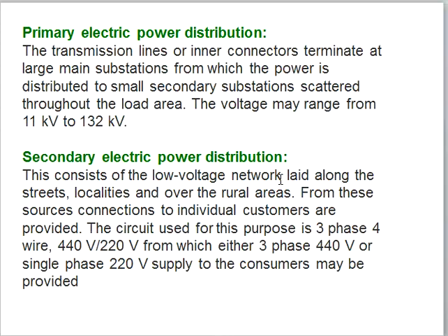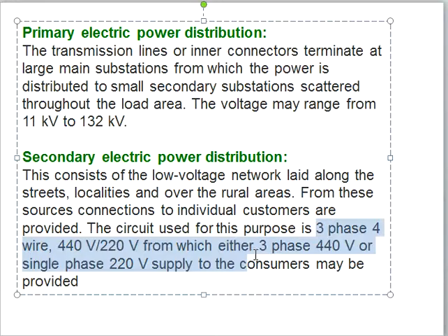The circuit used for this purpose is three-phase, four-wire, 440 volts, from which either three-phase 440 volt or single-phase 220 volt supply to the consumer may be provided.